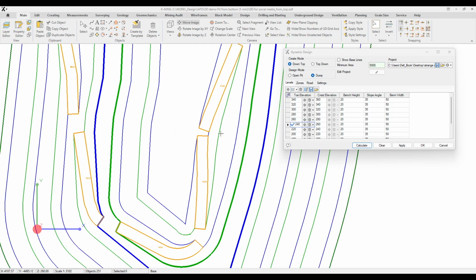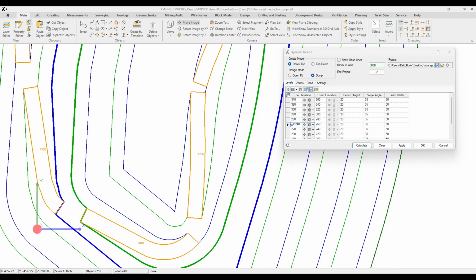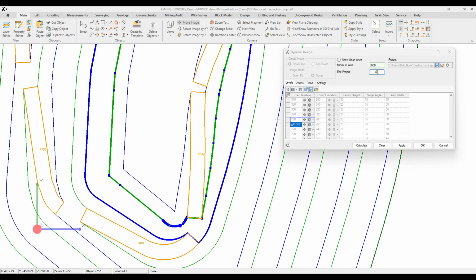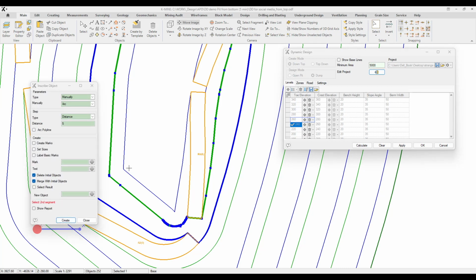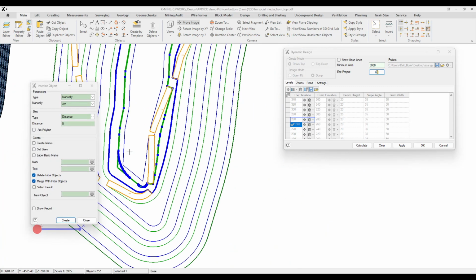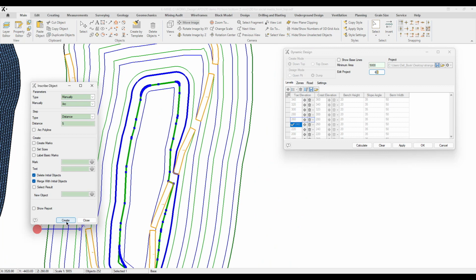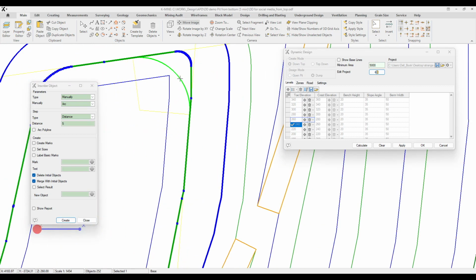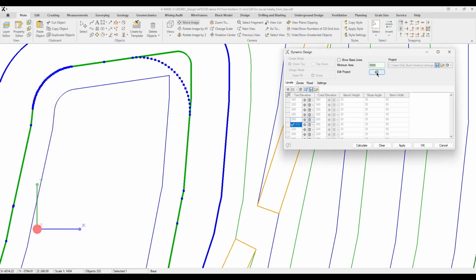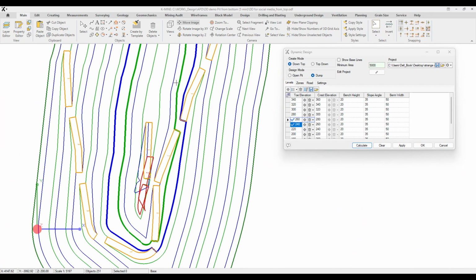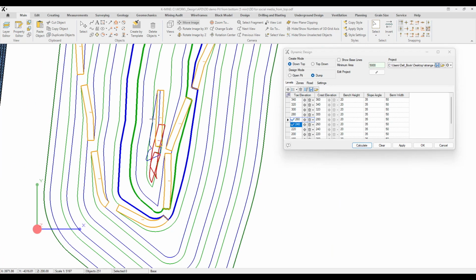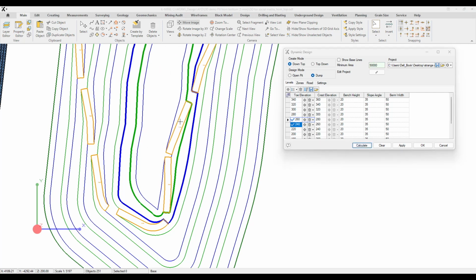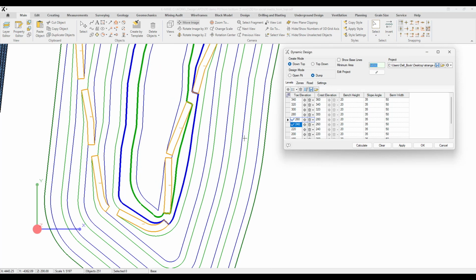After adding another road, we adapt it to the design. As a rule, when we adapt the design to match the most realistic dumping or mining conditions, all ramps are in the right position. Let's smooth the angles and remove inconsistencies. Commands such as add vertex, delete vertex, move vertex, inscribe arc, smooth line, delete part of line, and similar ones are perfect for this task.